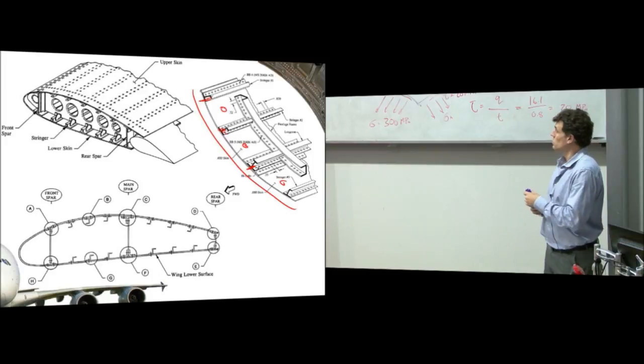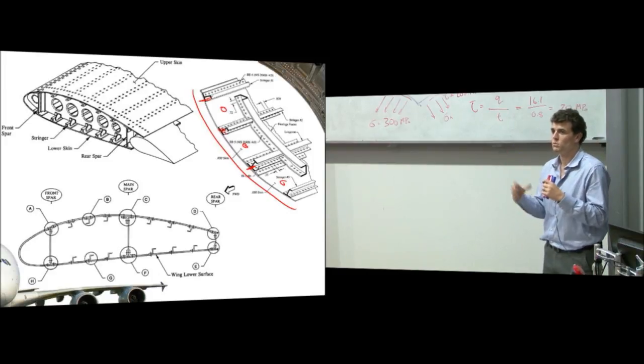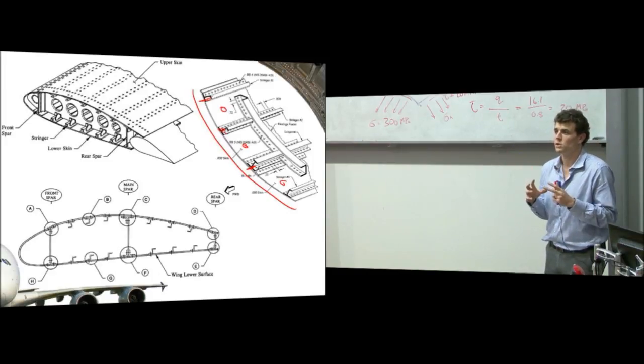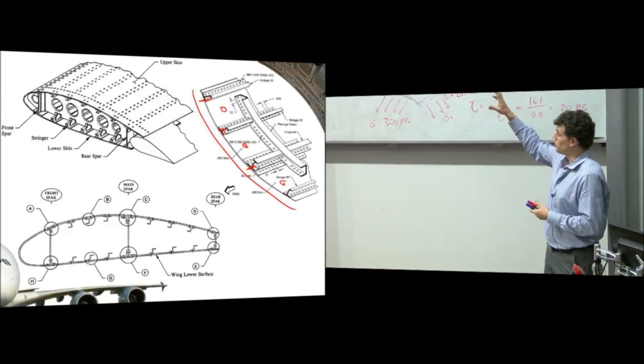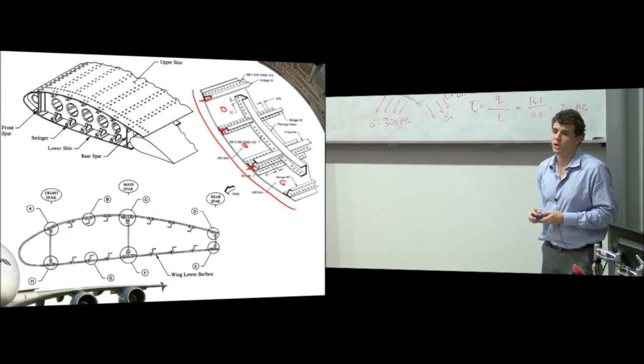And I'll give you some geometry for a fuselage, some moments and some forces on that section, and then you can go in and actually work out all the boom idealization, what the stresses in the panels are, what the stresses in the members are.